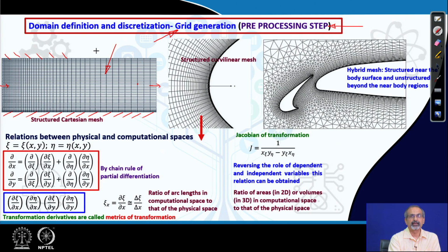Now, in finite difference calculations, we look at the grid points, and we make use of the differential forms of the governing equations, and then we try to approximate them at these grid points. While in a finite volume technique, for example, we will talk about these different control volumes. I have marked one of them, and then we try to use the integral form of the governing equations on each one of those control volumes and try to work out the flux transports which are happening across the different faces of the control volume.